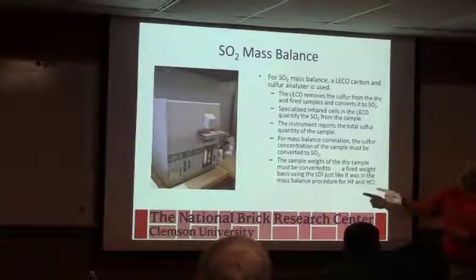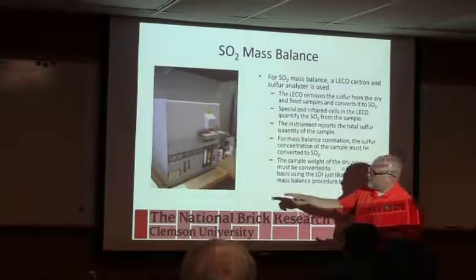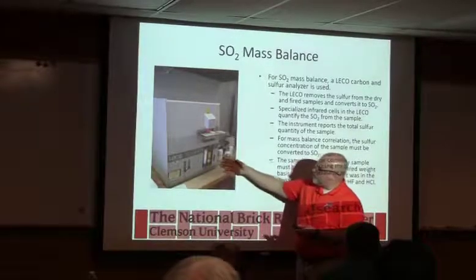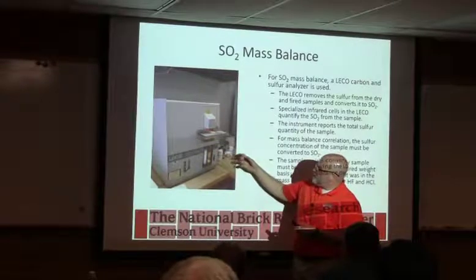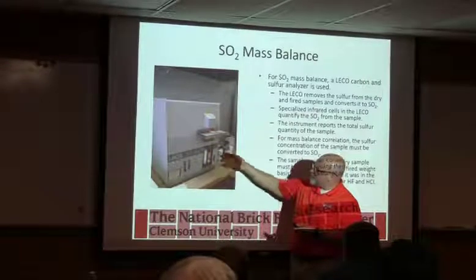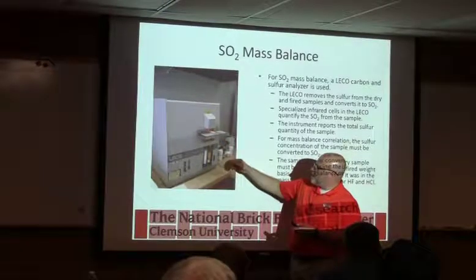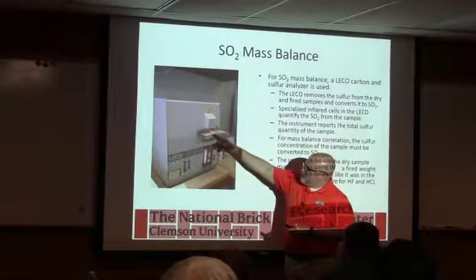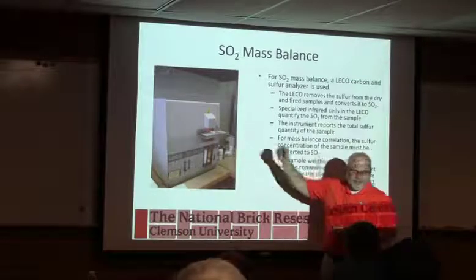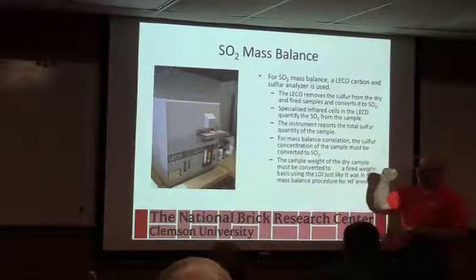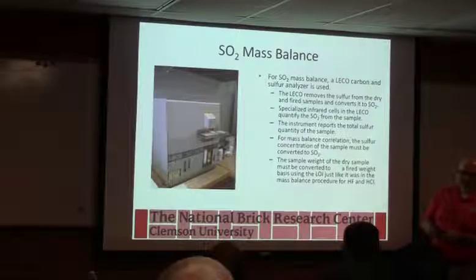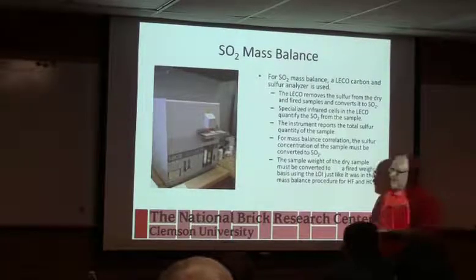Jim here's got the same instrument. This is a LECO carbon and sulfur analyzer. This is how we measure carbon, sulfur. We can differentiate sulfides and sulfates, organic carbon from carbonates, depending on how we set it up. But basically, it's a tube furnace, and I'm not sure what it is in Fahrenheit, but it sits at about 1375 Celsius, so really hot.